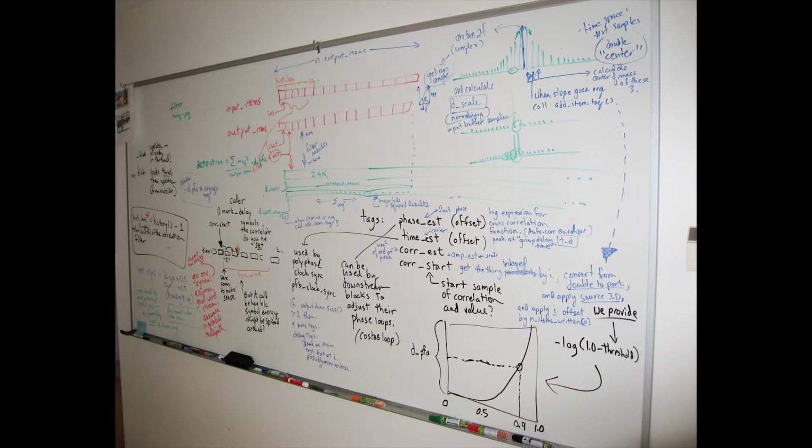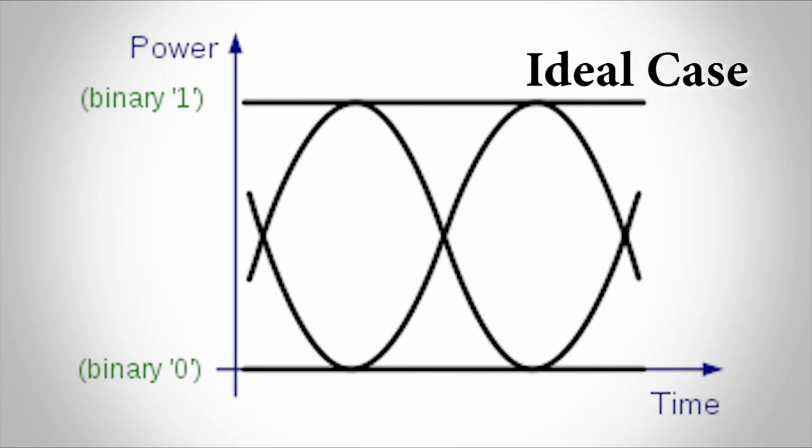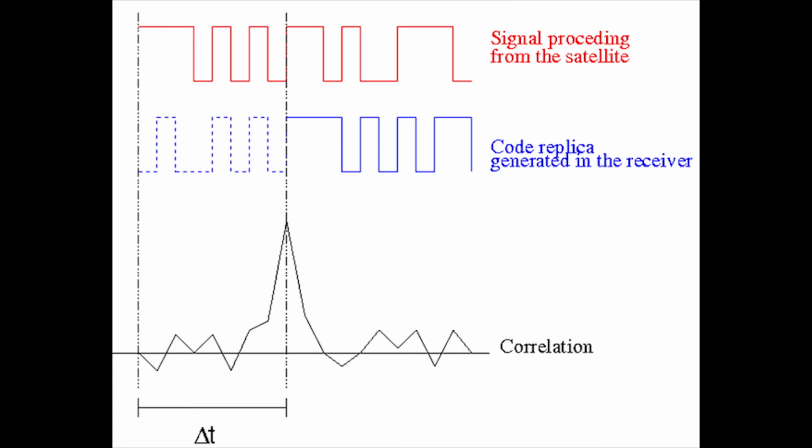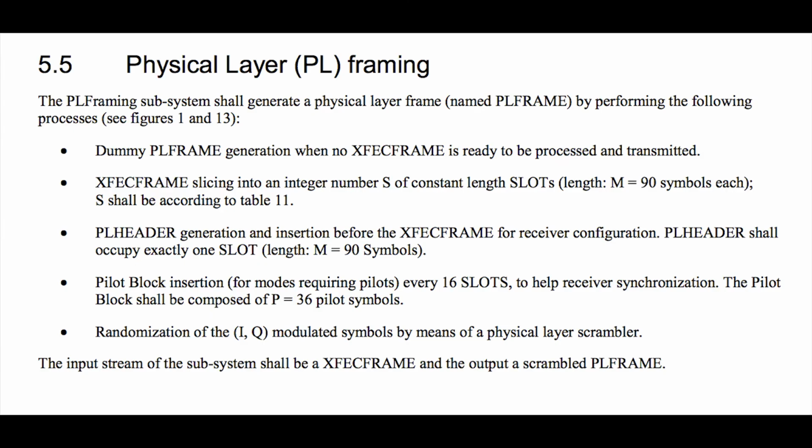Greetings! Today we're talking about our simplified pi over 2 BPSK decoder, working under the assumption that symbol timing and phase have already been resolved to a single sample per symbol. This work fits into the much larger picture of acquiring phase, timing of symbols, demodulation, decoding, and correlation to the fixed patterns of the start of frame field in the physical layer header that helps define each DVB-S2 frame.